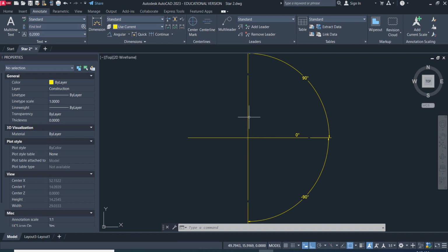What I've got drawn here is a coordinate system, set of crosshairs, whatever. I got a vertical line and a horizontal line. In AutoCAD, under its normal settings, 0 degrees is to the right of the x-axis, okay? Any angular degree that you, now these are not dimensional degrees, like when we would dimension a drawing, but the degrees used when we're creating a drawing. So 0 is always to the right.